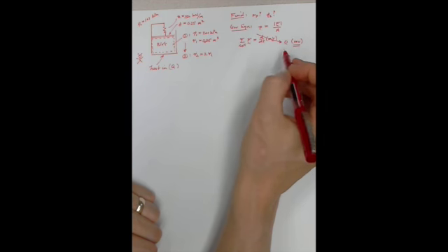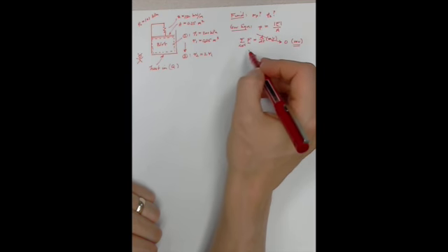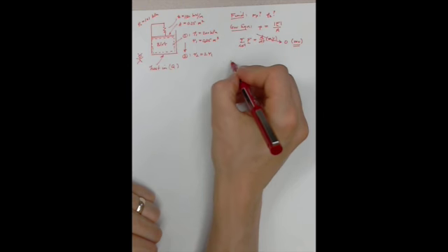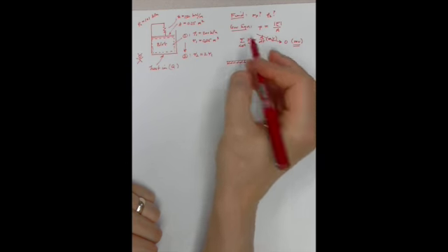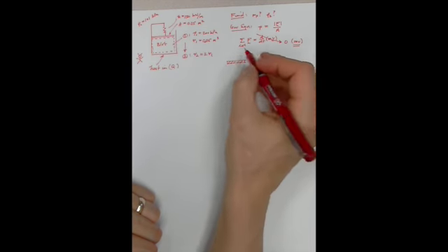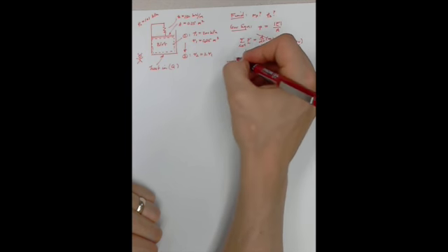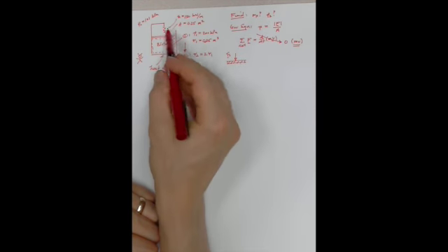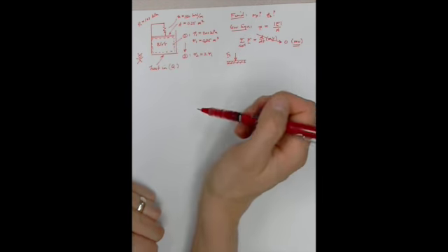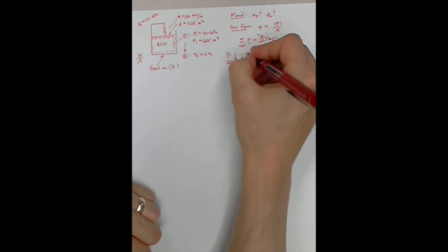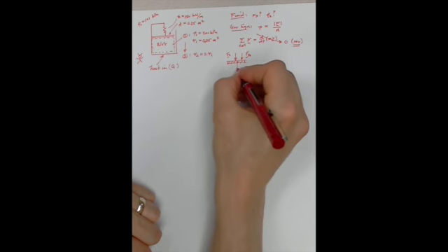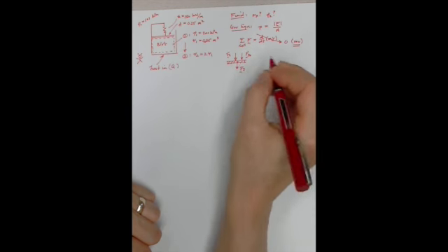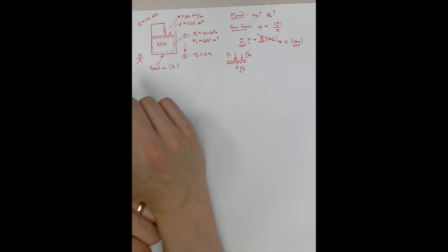So this is our governing equation from last time, and in order to use it, we need to have a system. In this case, the system that we're going to choose is the piston head, not the blob, but what the blob is pushing on. The piston head has a number of forces at work on it. It has a spring force that's going to be pushing on it from this spring that's going to be compressed. It has an atmospheric pressure force. It has a force due to gravity pulling on the mass of the piston head itself.